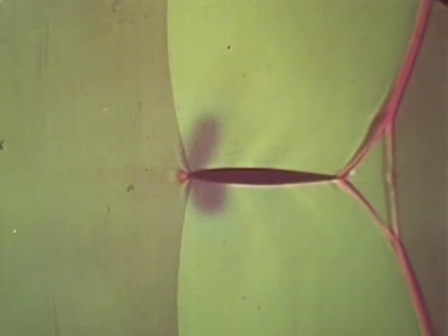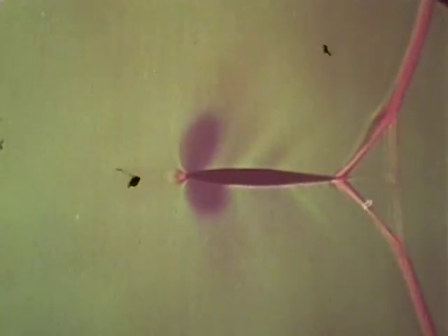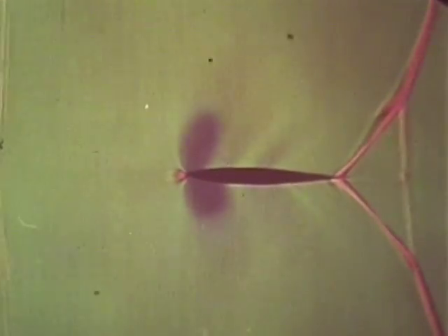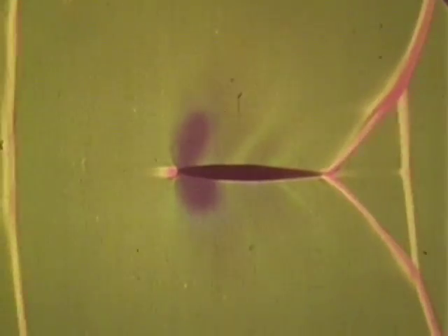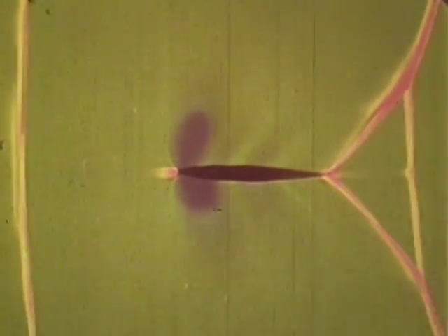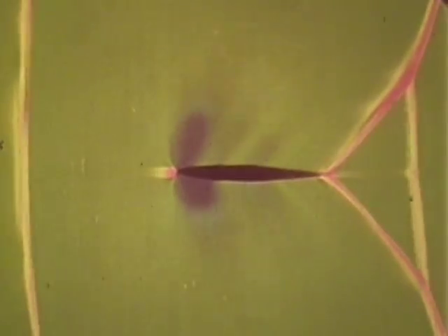As before, light green is used to show the supersonic regions. The flight Mach number has just passed Mach 1. The free airstream is supersonic now, and another shock wave appears in front of the wing, the bow wave. It's something like a bow wave on the surface of water.